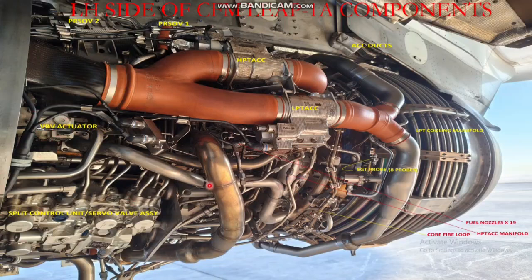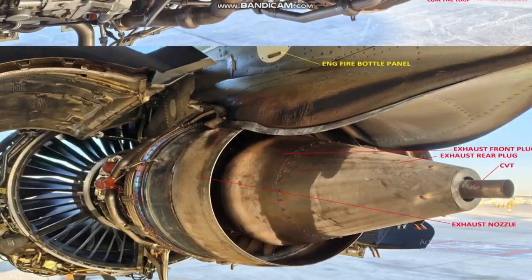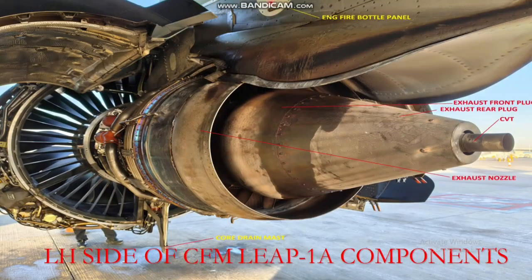So I think in this we have only this many components, and here you'll find there is an access for the fire bottle panel. This is just a cooling hole vent, so that air will go inside the pylon area. And this area is also your heat blankets for the cowl, because this complete portion is hot, so it protects the composite structure. This is your exhaust nozzle. Forward is the exhaust nozzle. This is your exhaust front plug. This is your exhaust rear plug. This is your CVT center vent tube, and this is your core drain mast.